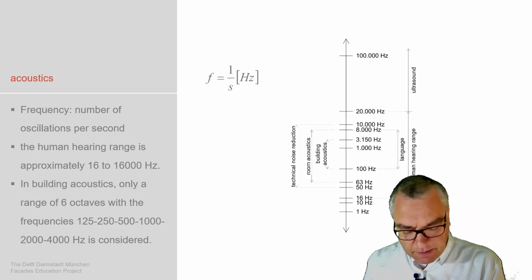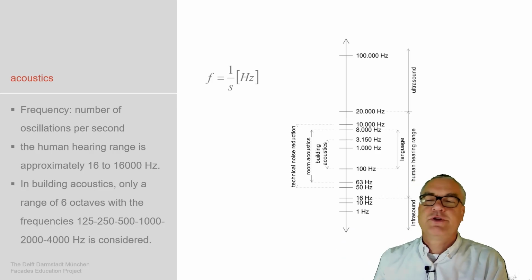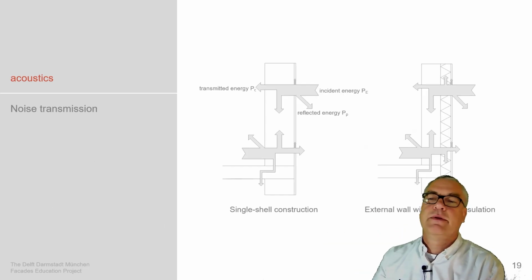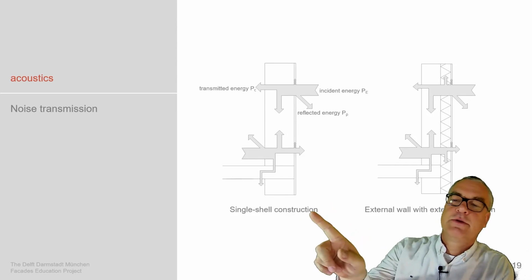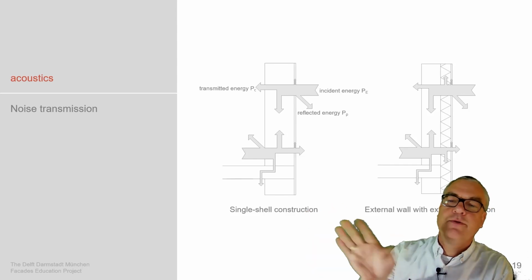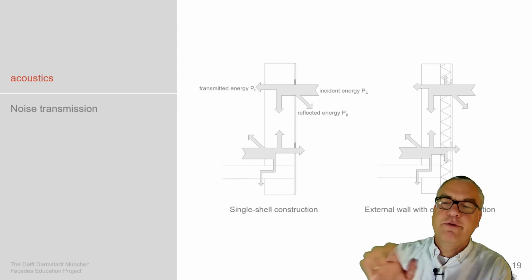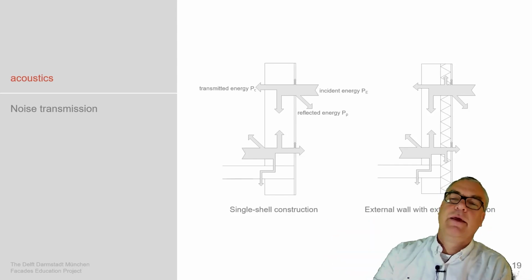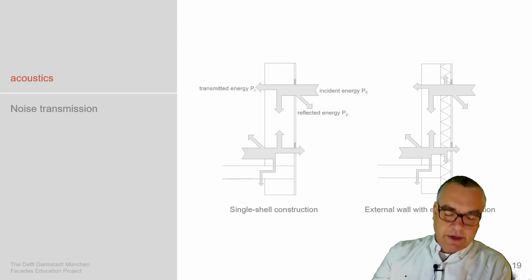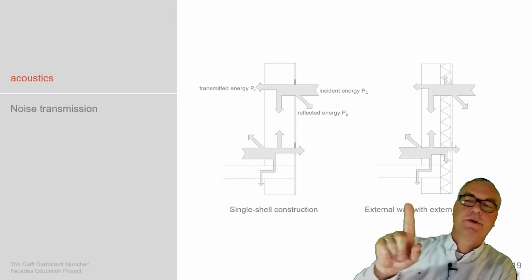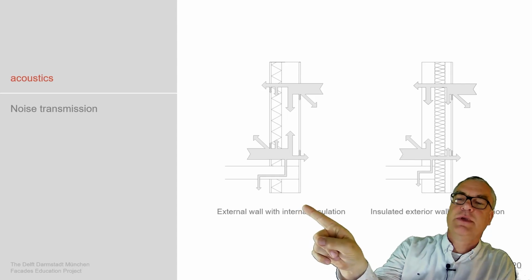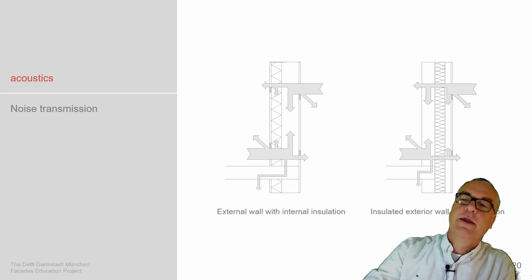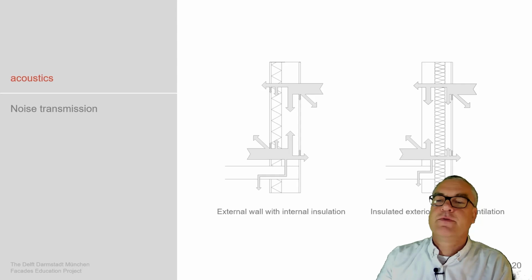And the simple saying is the heavier a structure is, the less this impact appears to be a problem. Which means that the solid structure in terms of acoustics works quite well. Low frequencies may be getting into trouble, but mainly the structure being heavy helps a lot. The outer insulation, which we see here, and then the inner insulation, which we see here, we see that through the light structure, the acoustics finds its way into the solid structure.